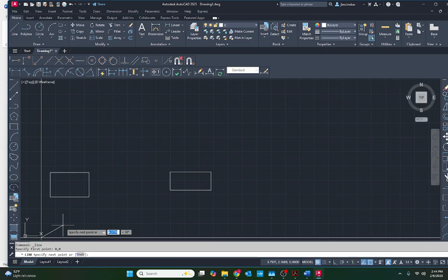Now, the way coordinates work is we have absolute references and relative references. When you type into the boxes that you see here on your screen, you're typing a relative reference. So this next point, if I make this line, if I type 2, 2, it's going to put the line 2 units to the X, or the horizontal, and 2 units to the vertical.